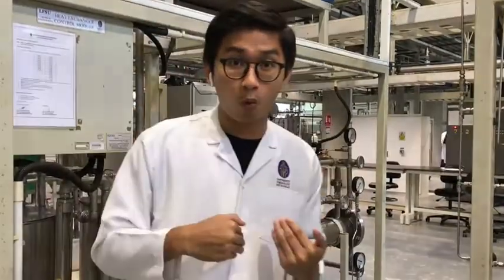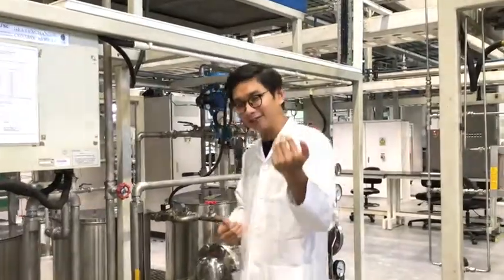And for your information, what happens if I increase the integral time, which is the I value? Once we increase the I value, the response time will be lower, so it will be faster. But for the D value, which is the derivative time, once we increase the derivative time, the response time will become faster.